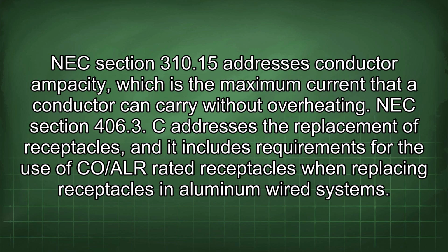NEC Section 310.15 addresses conductor ampacity, which is the maximum current that a conductor can carry without overheating. NEC Section 406.3(C) addresses the replacement of receptacles, and it includes requirements for the use of CO/ALR rated receptacles when replacing receptacles in aluminum-wired systems.